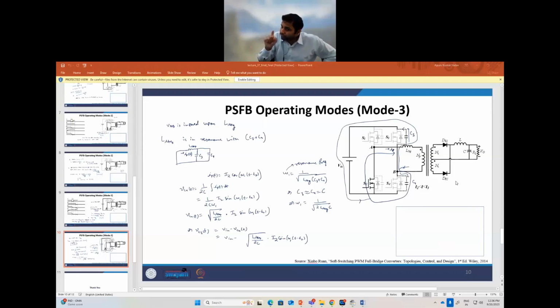However, if you use SiC or gallium nitride, you will see that the zero crossing problem will be less compared to the IGBT case or silicon MOSFET case. You can change the IGBT or silicon MOSFETs to silicon carbide MOSFET or gallium nitride MOSFET. Yes, I will try.